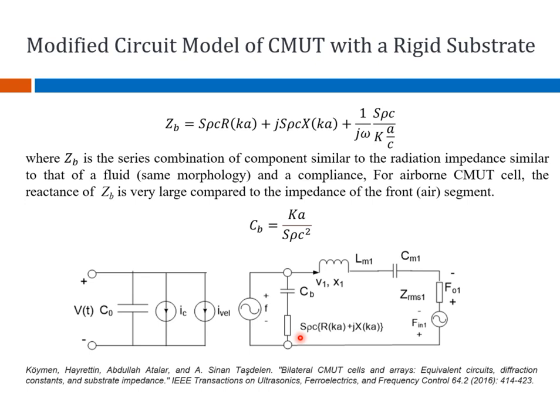Because the longitudinal speed of sound in glass is up to 6,000 meters per second, as compared to 340 meters per second in air. So the longitudinal propagation is going to have a very large wavelength, right? The shear waves are about half that speed of longitudinal. So this loss is representative of the vibrations in the backing material.